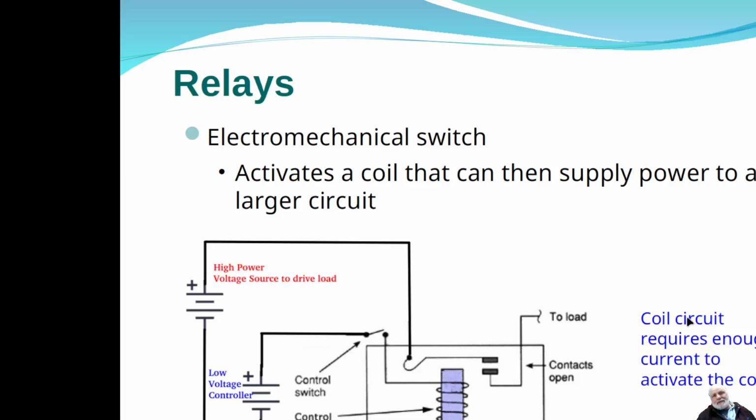Nothing near like what's going to drive your load, but depending on the size of your relay, it could take several hundred milliamps all the way up to even an amp, depending on exactly how big this relay is. It could take a significant amount of current to drive it, and then it's also storing that energy in the magnetic field.